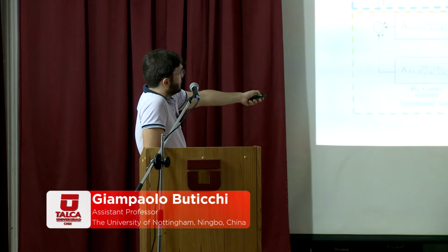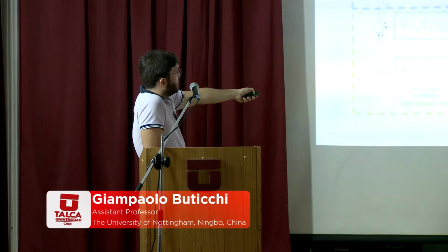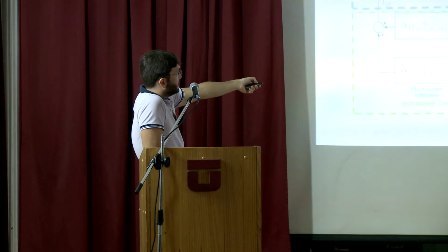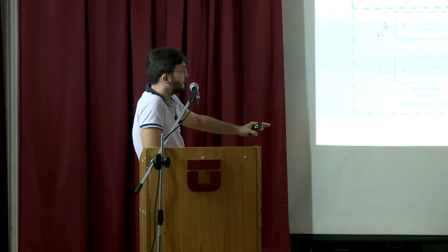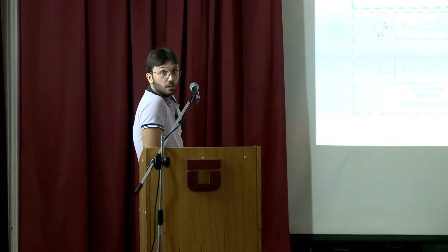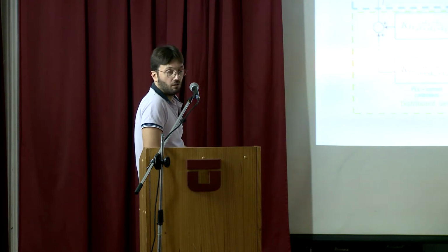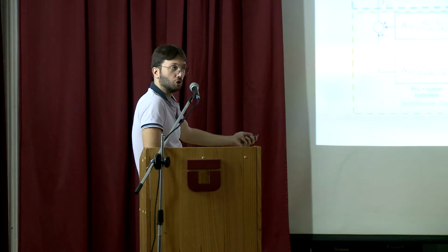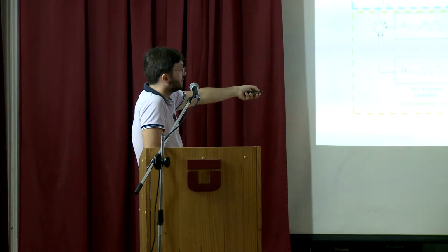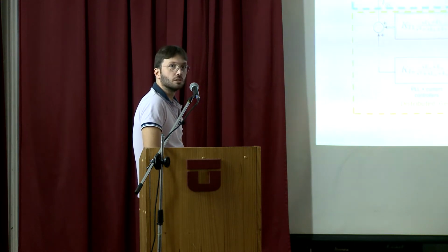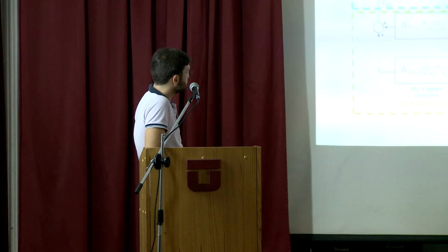But still, with reasonable values, the system, just like this, is stable when the bandwidth of the PLL is above 5 Hertz. And 5 Hertz is a very reasonable value. Usually for commercial products, it's above 10. So with normal converters, this can actually be applied.